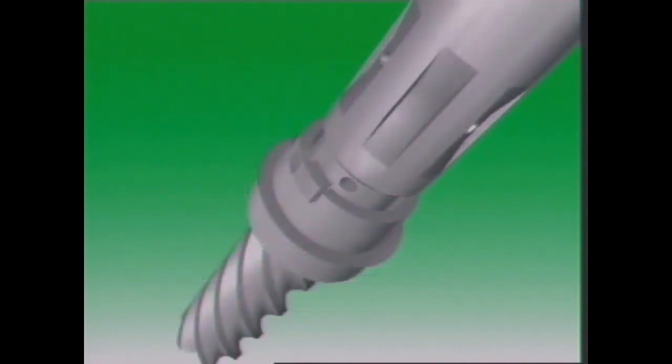The input shaft can twist through only a small angle before it contacts a stop on the pinion gear. This is needed to provide manual steering when power assistance is not available.